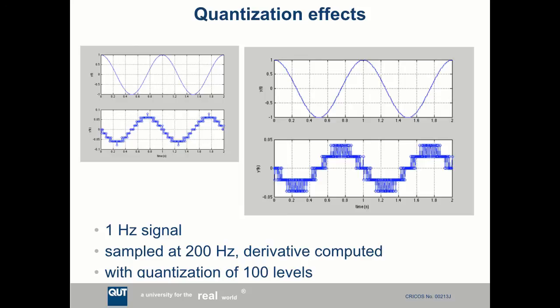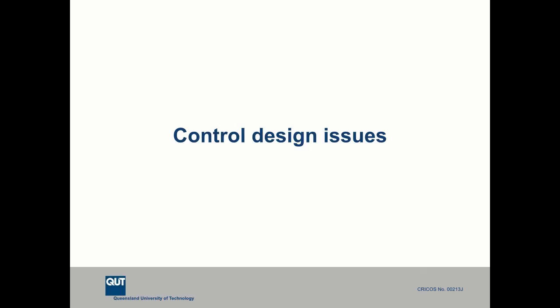So this is a reason why you can't just crank up sample time and say it's going to get rid of all my problems. If your signal's quantized, and almost everything we deal with is quantized, right? The signals we measure come in through an A to D converter, they come in through an incremental encoder on a shaft, they're all quantized. Quantization in time interacts very badly with quantization in value, right? So this is getting to be a really big trade-off of lots of different things. Just park all these things in the back of your head. Maybe you'll need them one day.